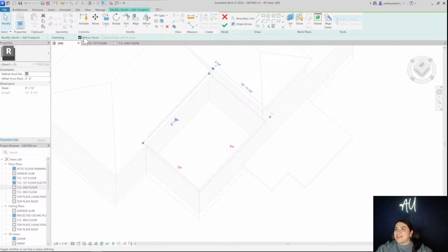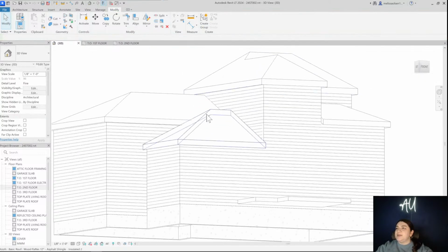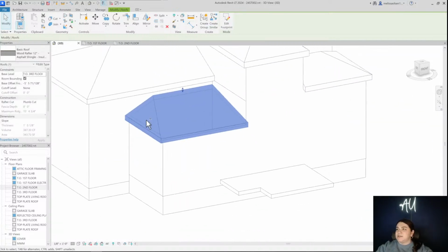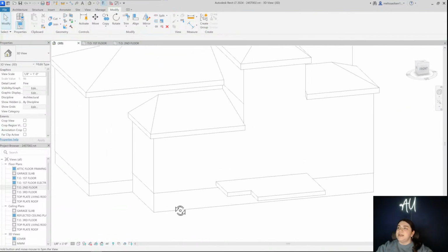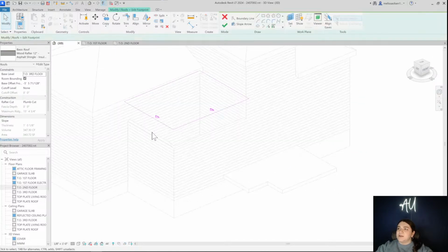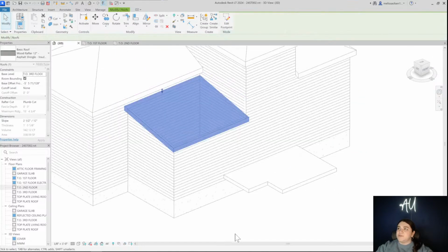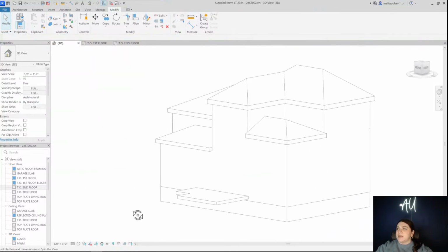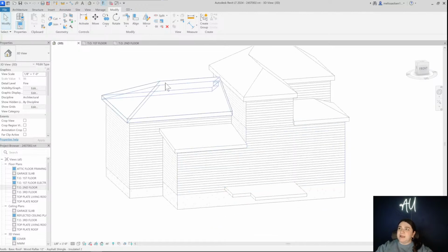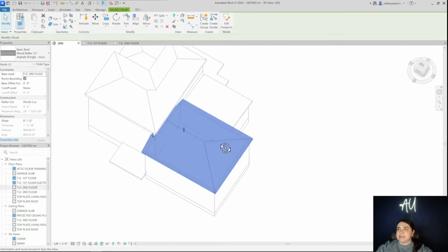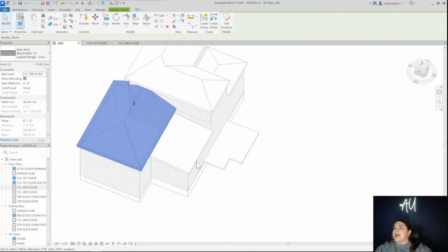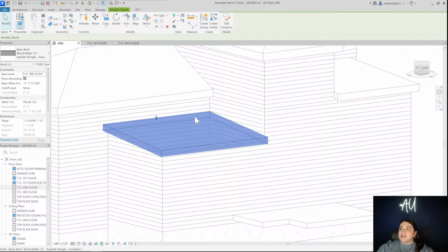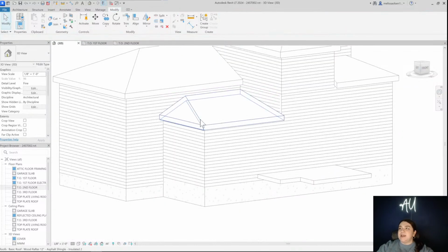So I'm going to uncheck this roof, and we're only going to slope these two areas. And then I'm just going to lower this down so that it meets like that. Now, that's an option. We could also uncheck this roof and just slope it this way. That's also an option. I personally think, because we're doing hip roofs everywhere, that I want to keep that style and not introduce a shed roof, which is what this is. So I'm going to undo everything I just did and leave that.